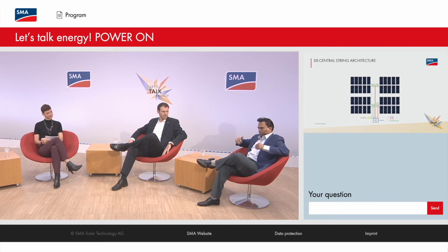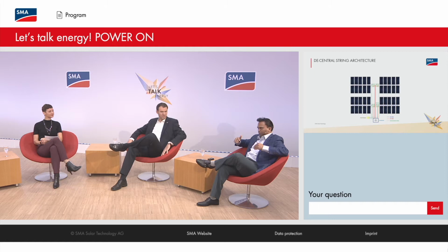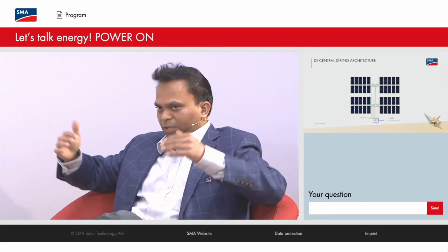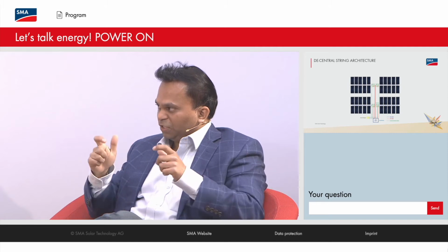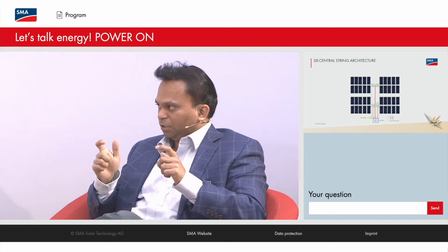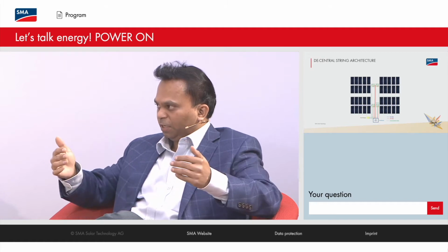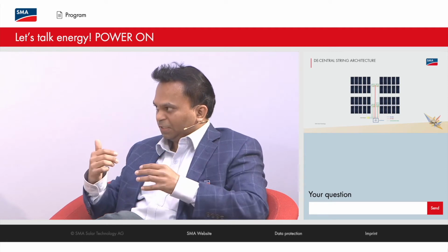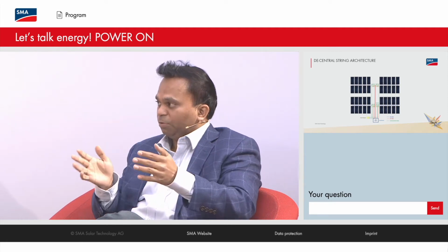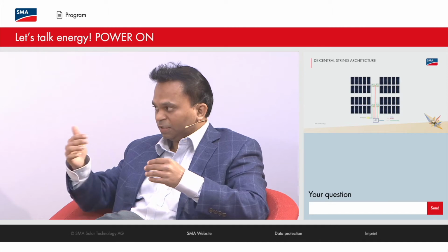The advantages are as follows. The DC cables bring the electricity to the inverter, and the AC cables are very short. So the losses of the AC cables are nothing. In an oversized DC field, these losses can be compensated on the DC side, but not on the AC side. So when you keep the AC cable short, the energy loss is minimized.